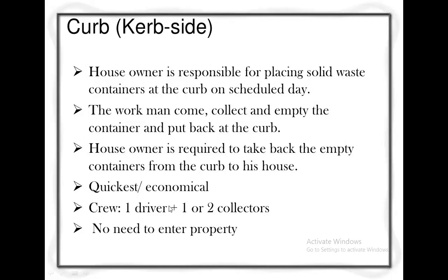It includes one driver who drives the vehicle that carries the waste, and there are 1 to 2 collectors to carry these containers, and they dump into the vehicle, and there is no need to enter the property. So this is a very economical and quick method of collection of solid waste.